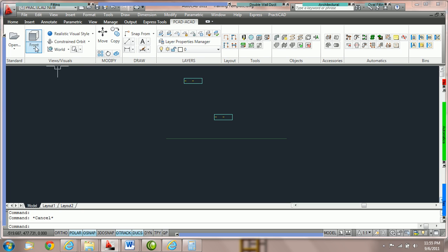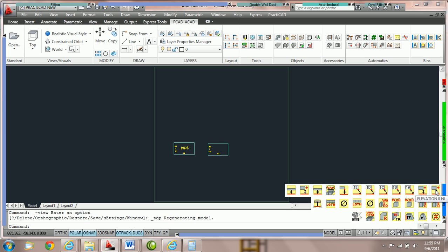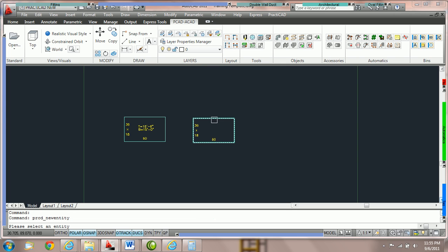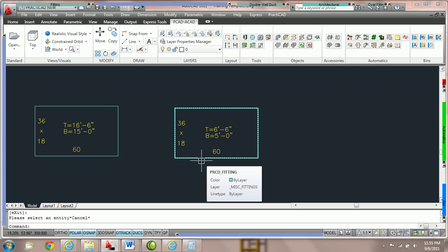Once again, if we go to tag the duct work using our elevation 0, the tag itself actually does the adjustment. So it represents on our drawing 5 foot as it represents 15 foot here. But our ductwork is actually at 35 foot and 25 foot from datum 0. So when we export this to Navisworks or use it for BIM modeling, it is correct. That is how to